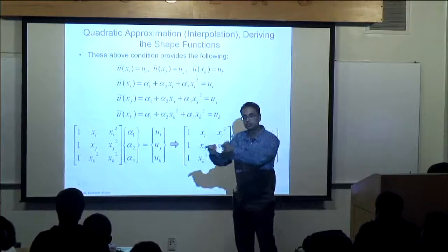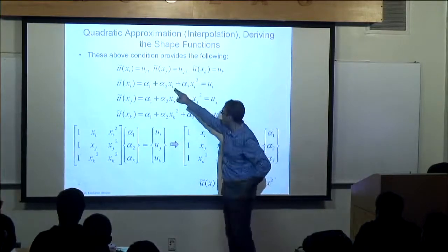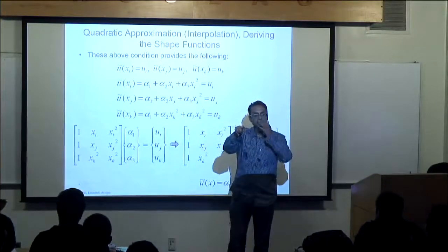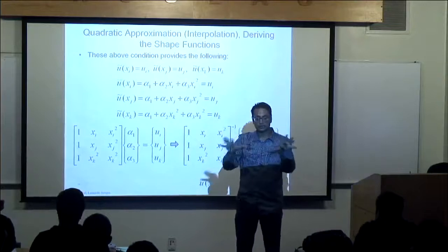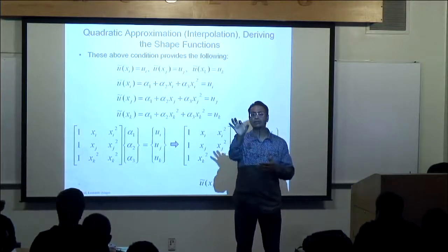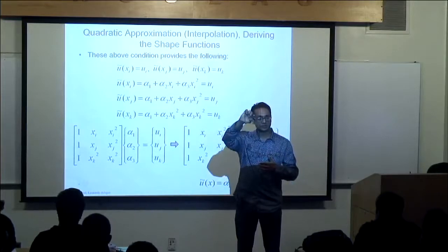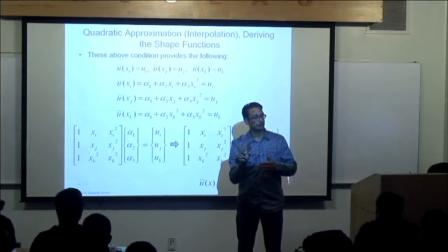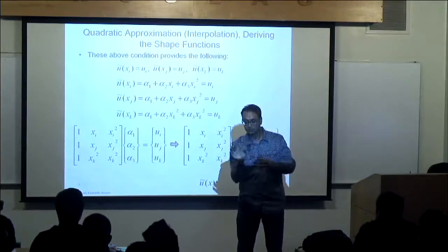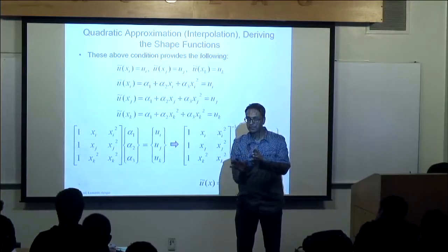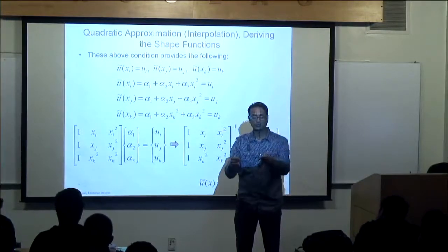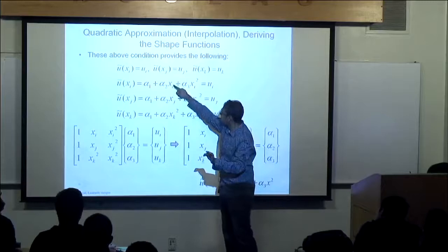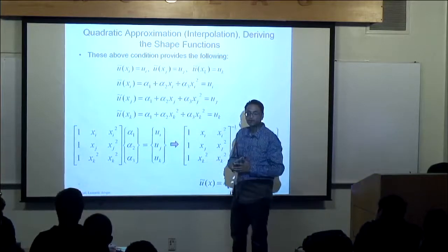It depends where the element is positioned, right? That's how this xi, xj, and xk is. How does that relate to Abaqus? In Abaqus, or Nastran, or whatever software you want to use, you have to define a node position, remember? That's a star node, and you define the nodal positions. And then the second step is to define the element connectivity, star element, and then you have the element connectivity at the bottom, right? So the element tells you what nodes go with an element, and those nodes have coordinates, right? That's how I know what's xi, xj, and xk. That's how I know this, okay?